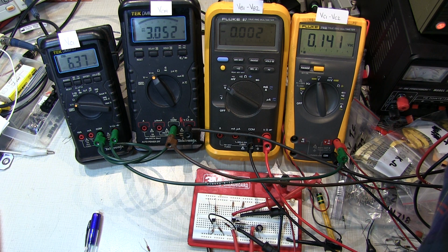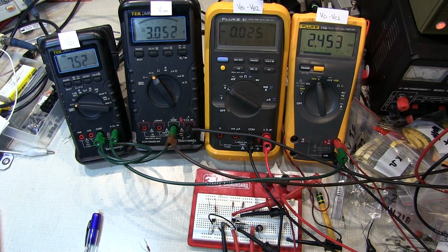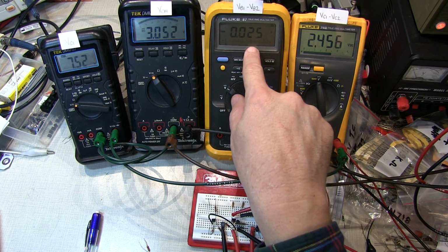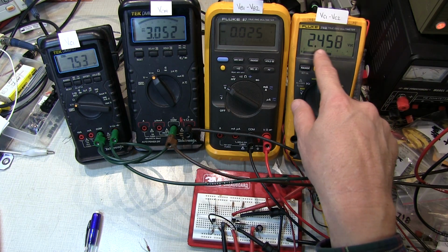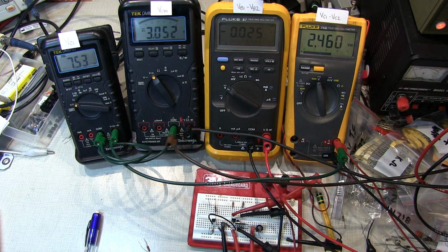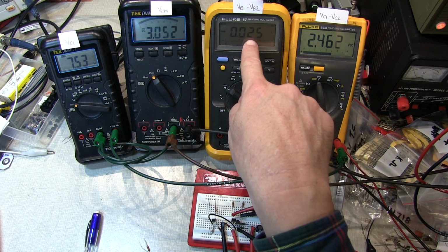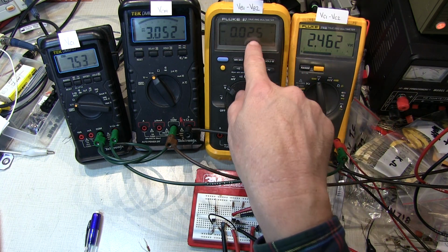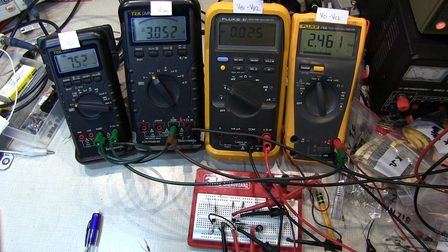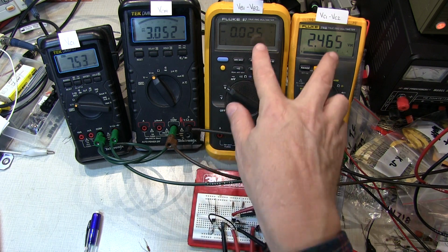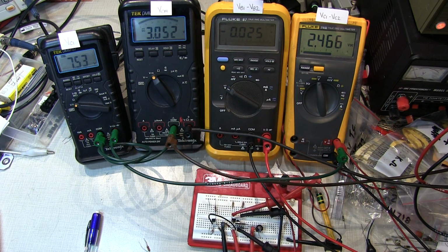So let's make sure that the gain is not changing either. Okay, so here's that same negative 25 millivolts going in, and it's giving me a 2.4, 2.45, 2.46 volt output voltage difference. Now it's not the same as what we had with the tail resistor in there because the current isn't the same. But the idea is that this set of voltages here, a negative 25 millivolt input and about 2.46 volt at the output, should be consistent regardless of where I set common mode.